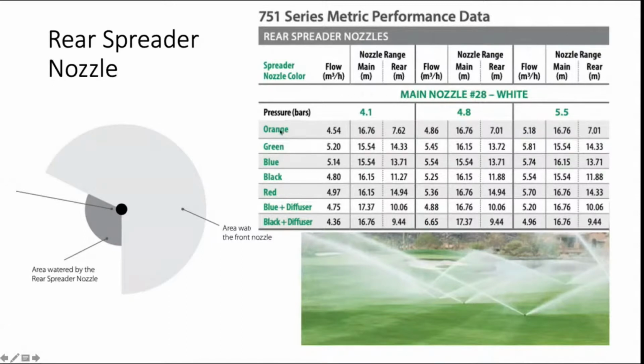But in any event, they show you by the color code that at a given pressure for a certain nozzle, as we increase the pressure, you see the flow rate increase here. The flow is going to increase with increased pressure. There's no surprise there. It's usually as a square root of the pressure. And then as you get a larger orifice, a bigger nozzle, you'll see the flow increase too, up to a certain point.